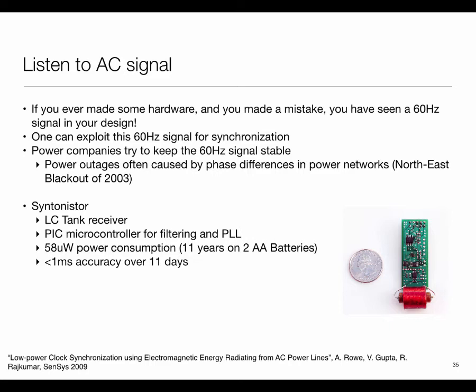If I want them to have a notion of time, then I can have some other mechanism to communicate with these nodes and tell them the time. So do a one-time clock offset correction, but after that they live off these relatively stable oscillators. This particular project used this for synchronizing sensor nodes down in coal mines, which is pretty deep inside the earth. So GPS doesn't work, WWVB doesn't work, but the AC signals are there, and so they made use of that. Could you think of other examples where timing information is out there?